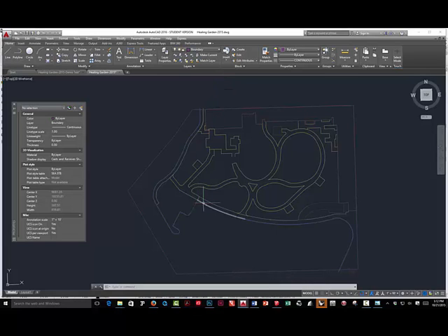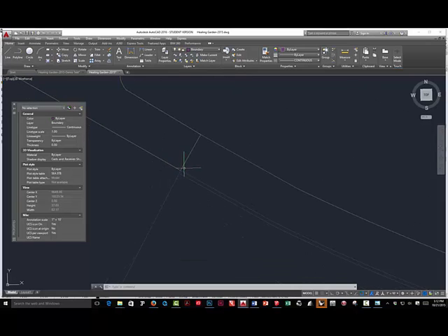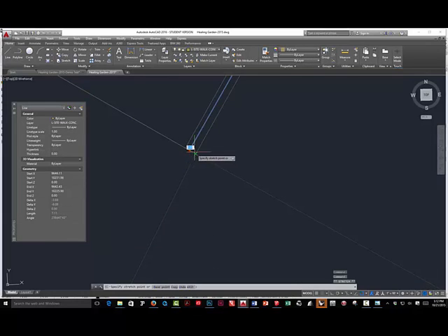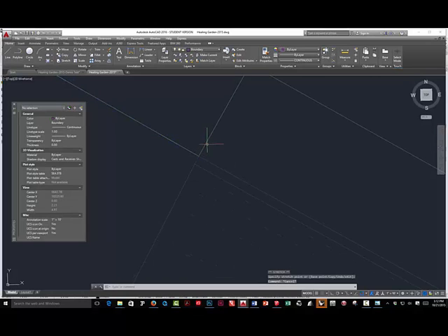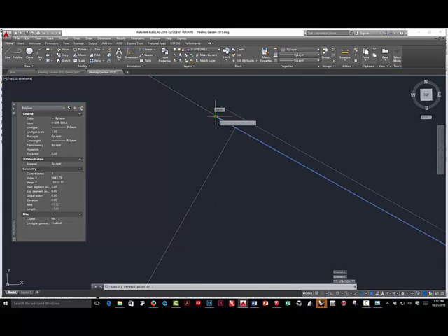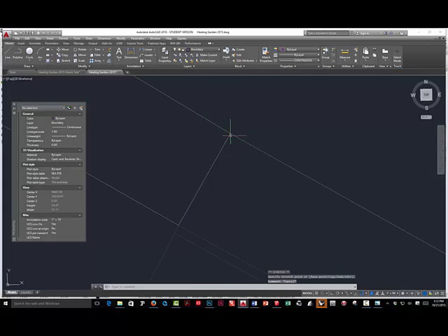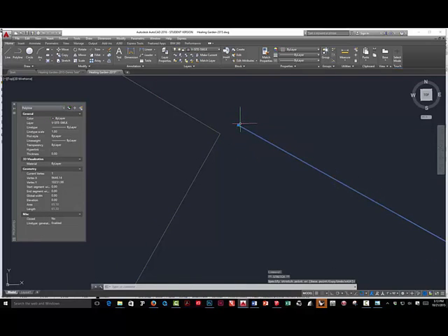Now, you'll also see a couple things that are not working so well. And this, I know this happens to be here, so I'm going to fix it now. This gets back to your drafting in AutoCAD. If these points don't line up, it creates an issue in SketchUp. So when you draft this up, make sure you use the object snap and everything fits together. If you have little lines like this that don't match that endpoint, that's not good either. I missed the line there. So I'm going to click on this, move it out, click on that, snap right to the corner, okay?